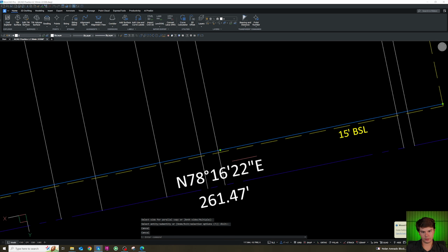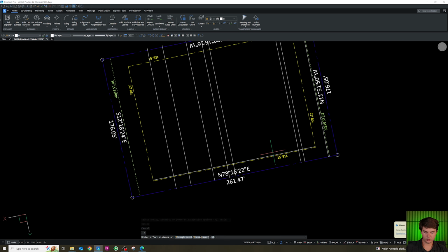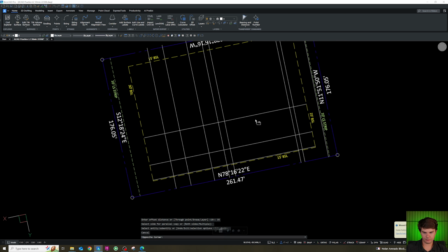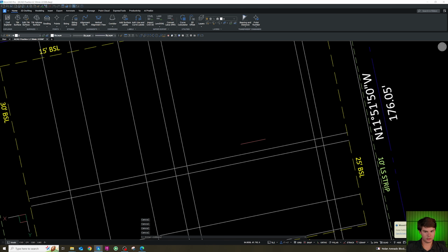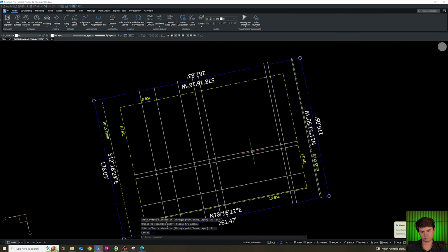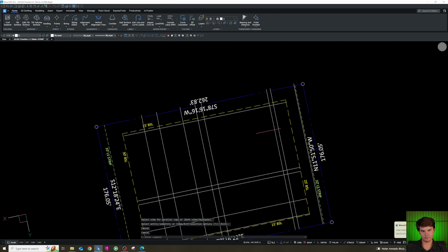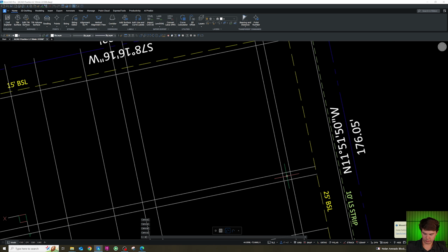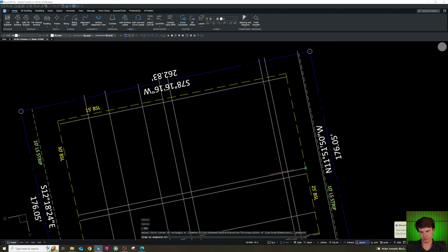Now from the bottom, we're going to do a 19-foot parking row, a 35-foot drive aisle, 5-foot hatch for the building, and an 83-foot building. Okay, now we have a spot for our building. I'm going to go ahead and draw the rectangle in.